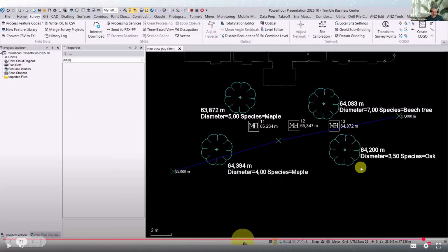And one last comment. This is just about the position and the existence of labels. This is not about calculation data. For example, if I change the prism height of a measurement afterwards, the locked features behave the same as non-locked features. The elevation changes as well, and the content of the text changes.